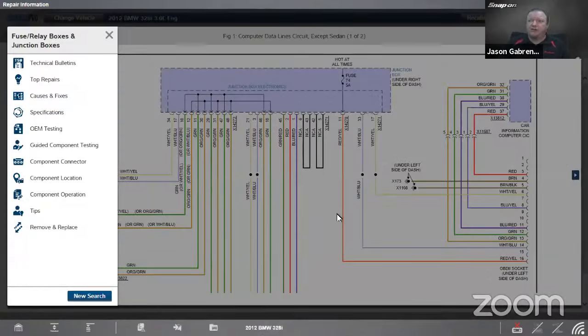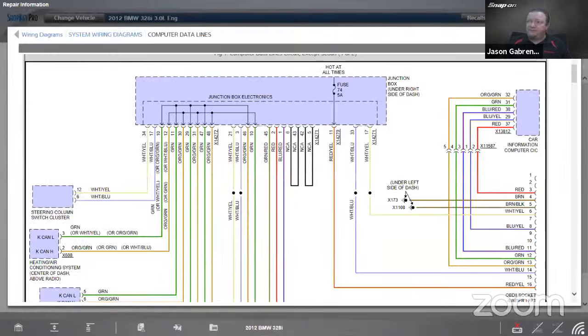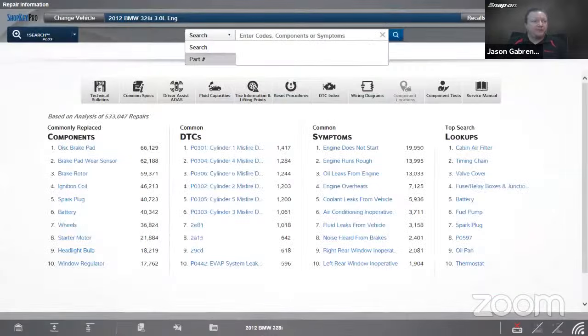So being able to check through a wiring diagram to see how this vehicle is wired, because if I had a communication problem here, we see everything goes in there first. So I'd want to check in this junction box first, and then I can also have a testing point for any of my other modules on the vehicle. So that just makes it a little easier to test. All right, so that is our week 1 of networking.